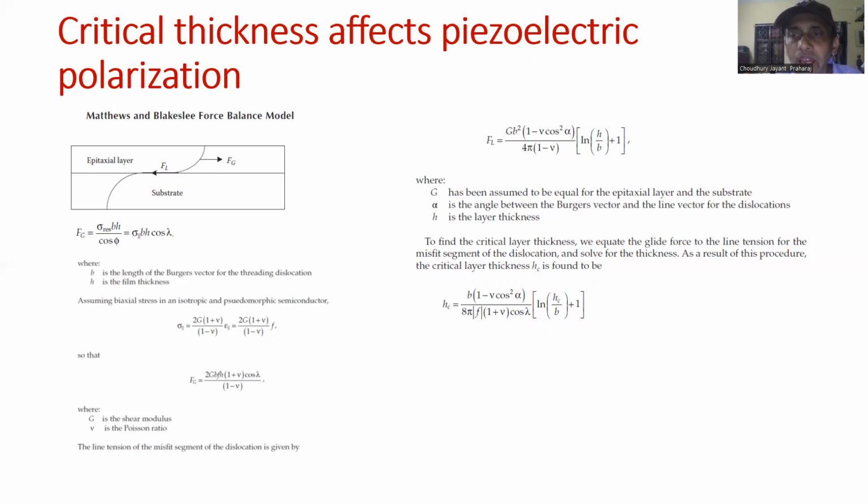So we need to keep in mind what the critical thicknesses are in this material so that we know whether or not we have piezoelectric polarization, and how much piezoelectric polarization we have in these materials as a function of layer thicknesses and as a function of composition grading in these materials.